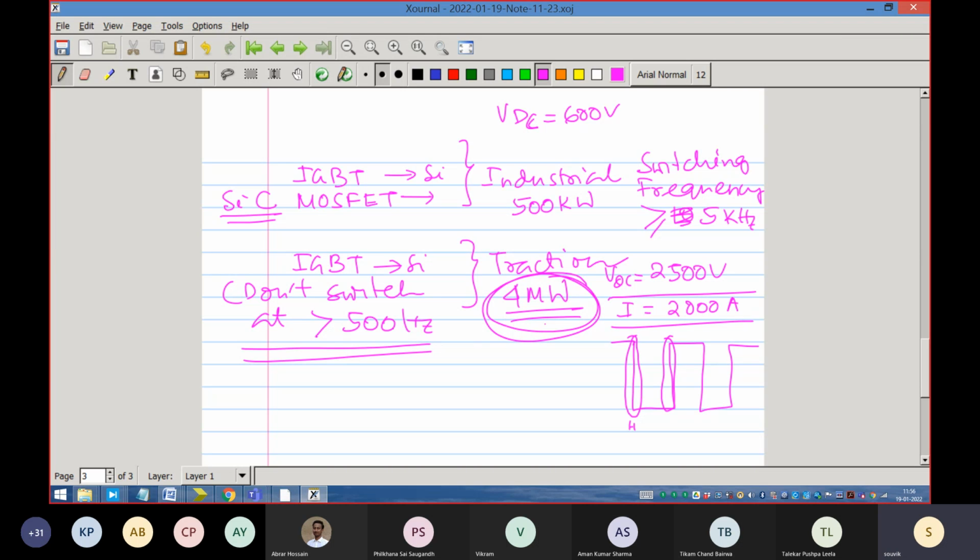So these are the issues we have to take into consideration, and understand that in the traction drive there exists a square wave mode of operation. Square wave mode of operation exists in this kind of devices so that the converter power loss is not so high, due to the losses in the devices at higher switching frequency when dealing with high voltage and high current, because the application itself requires a lot of tractive effort. So the machine and the system is at megawatt level, 4 megawatt, 5 megawatt, things like that. And that requires semiconductor devices which have higher switching time.